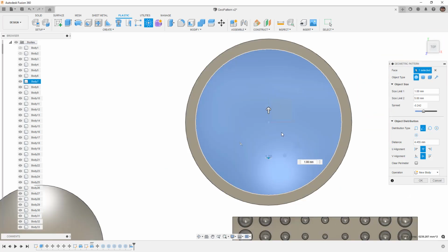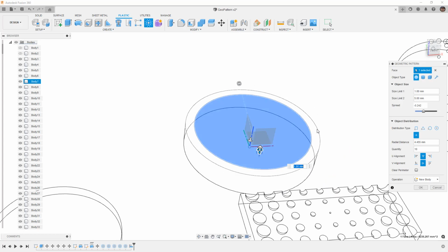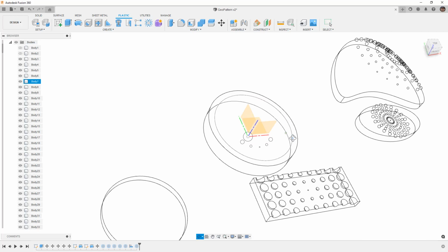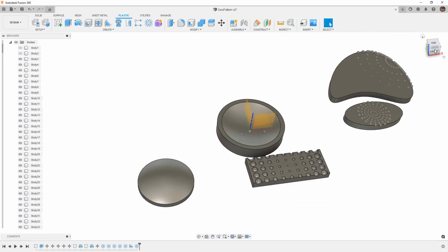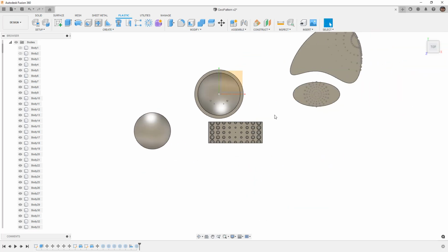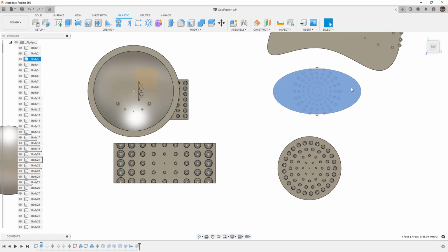So now that this is completely at the origin, I'm going to go into my wireframe display and start to manipulate some of these values. So if I go to a cylindrical or circular pattern or radial pattern, again, you can kind of see that we're not really getting the preview that we would expect, even though we moved it to the origin. So just something to keep in mind that it is potentially problematic with these convex or concave revolves, but it does seem to work on all the other faces, even though there are some potential issues with extents that you might need to go in and fake with a larger shape if you want to, say, remove a radial type pattern from a shape like this.